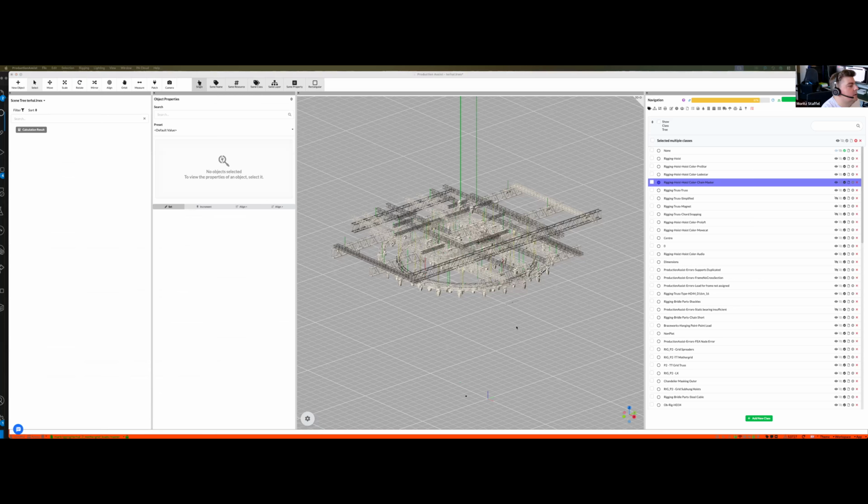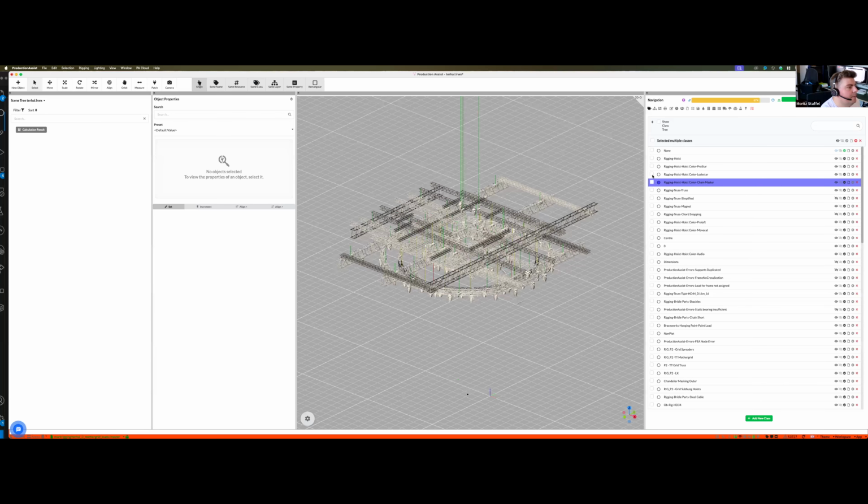Another thing which is quite nice in here is, if you now go to the calculation results and you click on the MB, for example, you can see the bending moments in here, and now you have an option to scale them. So if you bump up the numbers every time you're doing this, it allows you to scale the things. This is quite helpful if you actually want to see some of the smaller cut reactions in here.